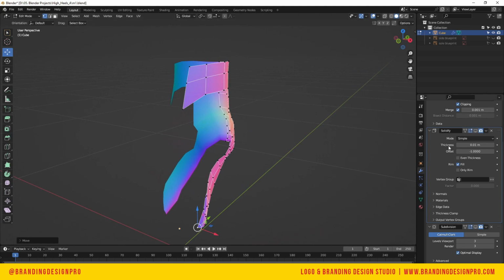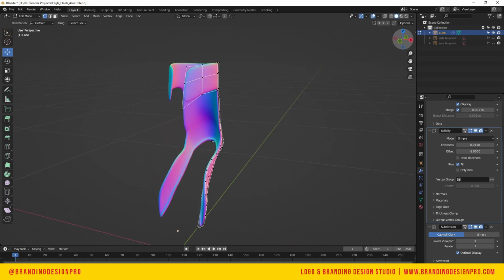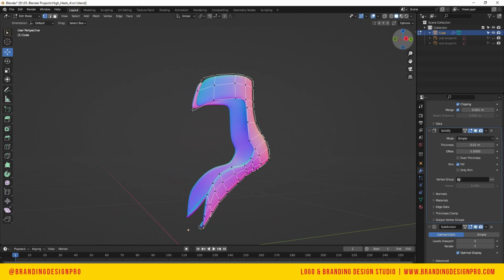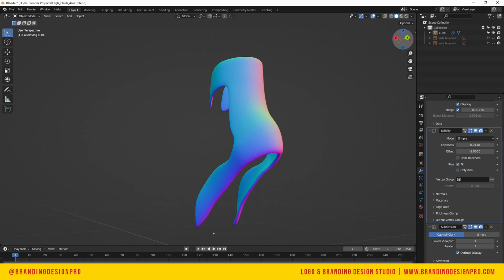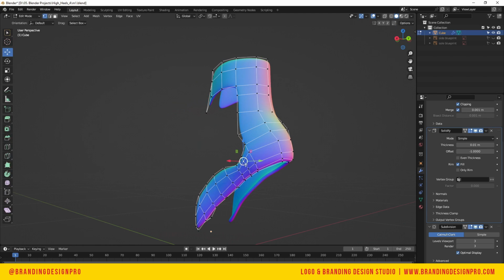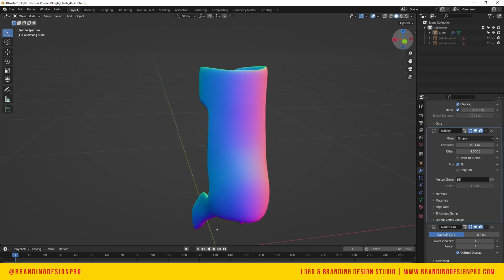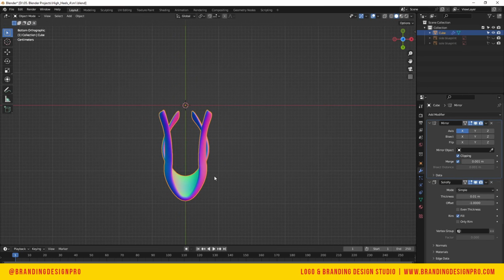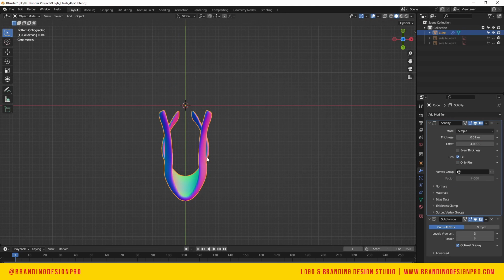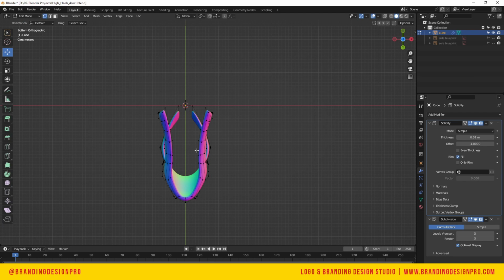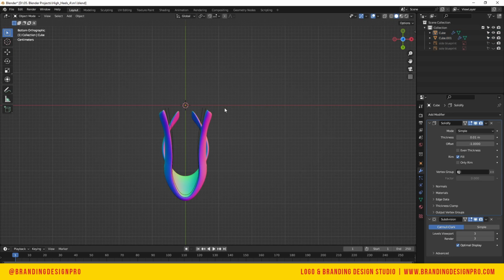Then we're gonna turn our vertex and then viewport mode on the right pad. And then let's see, we're gonna do the same thing, dissolve that edge right there. We're gonna hit Control 7 to go on the bottom view, bottom orthographic view. We're gonna apply the mirror modifier, come back down here and hit Tab, and then go to the edge selection mode, select the edge, hit Shift D, P, right click, and then P, separate by selection.